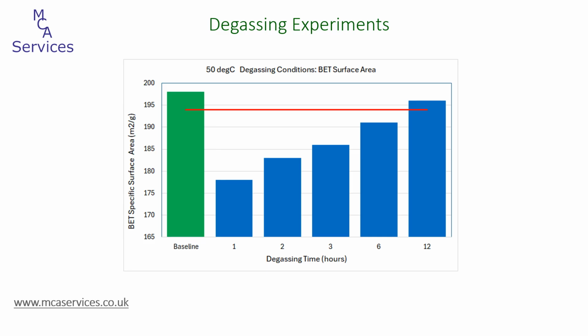Given the necessity of complete degassing, it's best to degas for a long enough period to ensure that all contaminants are removed. And it's actually quite common to see instructions and specifications with 16 or 18-hour degassing, which equates to an overnight period.